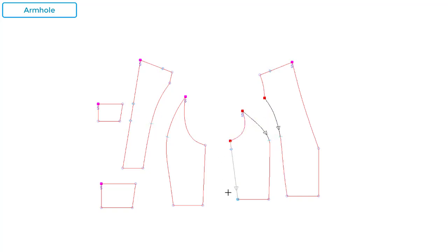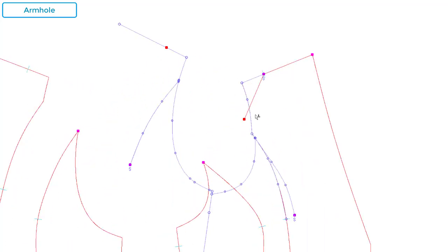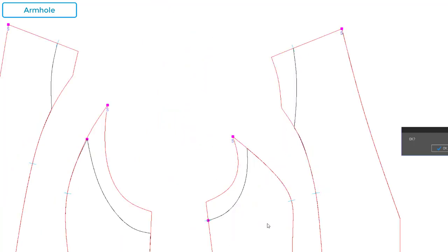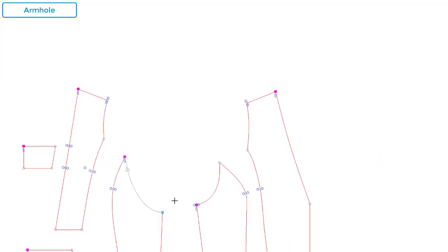The sewing alignment feature lets you visualize how the pieces will look once stitched together. For each piece, be sure to select the seam line from the notches all the way to the armhole. Once you've completed your selections, you'll see a stitch-together preview like this. Length matching can be done at the same time, allowing you to work more efficiently. Let's use this image as a guide to draw the armhole line. As you can see, the lines you draw are copied onto each respective piece.